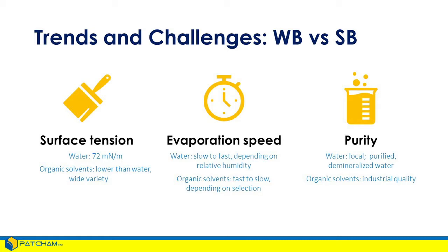Now, organic solvents' evaporation rates are independent pretty much of relative humidity, but yes, they are dependent on temperature. So the higher the temperature, the faster the solvent evaporates. So that means when you formulate, you can increase the amount of slower organic solvents when the temperature is higher for the summer season, and then increase the amount of faster evaporating solvents for the winter time.